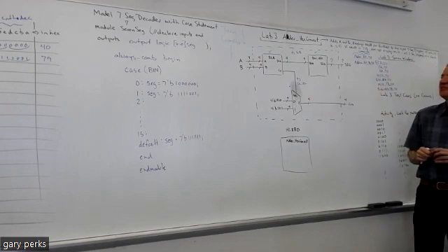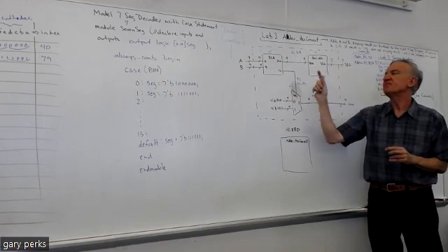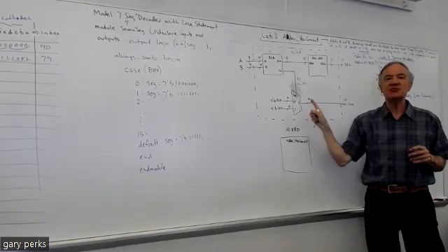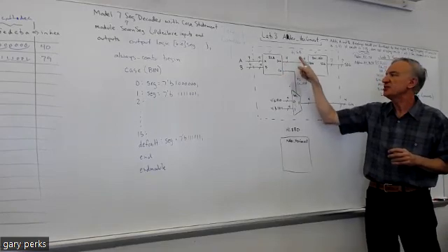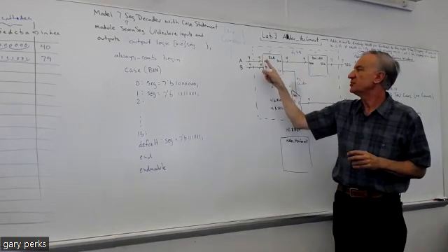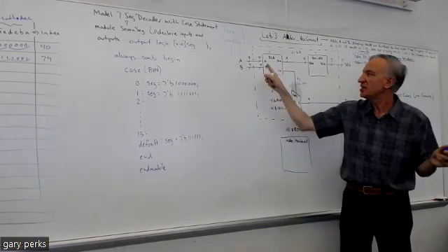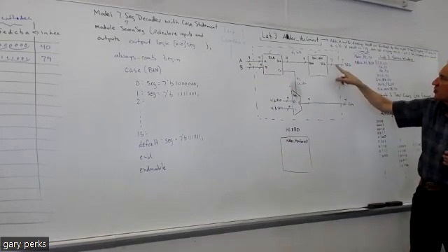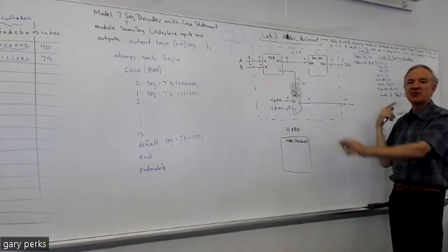Okay, but I just wanted to emphasize these internal signals, because remember, in Verilog, when you're connecting lower level modules together, see how this lower level output's going to this lower level input? That's when you need an internal signal. When you're connecting lower level inputs or outputs to higher level inputs or outputs, you don't need an internal signal. So that's why you don't see any T1, T2 over here or over here, because we're connecting lower level to high level, right? Outside the box are the higher levels for the overall circuit.